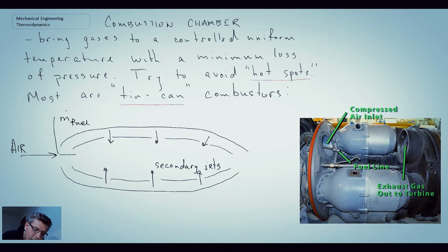And then there are different ways that they will use to maintain the flame in this combustion region. Sometimes there's a swirl combustor where you get a vortex, and the vortex has an induced velocity upstream, and you can kind of hold the flame there. Other times they'll have a bluff body here, and the wake within the bluff body is what maintains the flame. Different technologies depending upon the vendor and the engine fabricator.